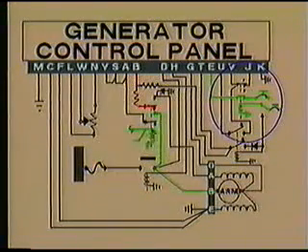The output control relay is energized during the engine start cycle from 0 to 55%. When energized, it disconnects the power into the control panel supplied from the B lead of the generator and the power to the field that will be provided through the generator A lead.